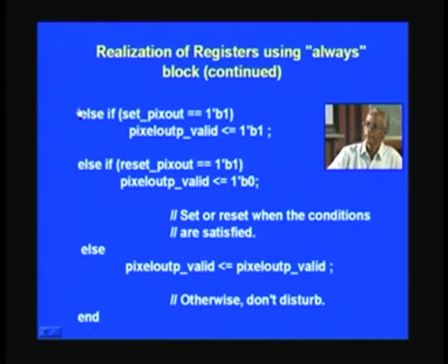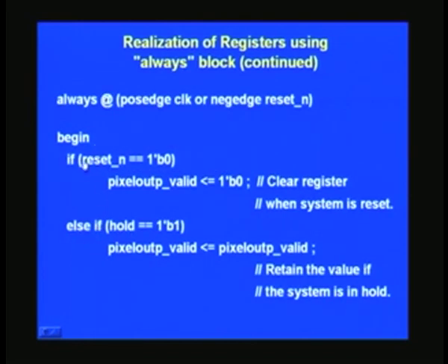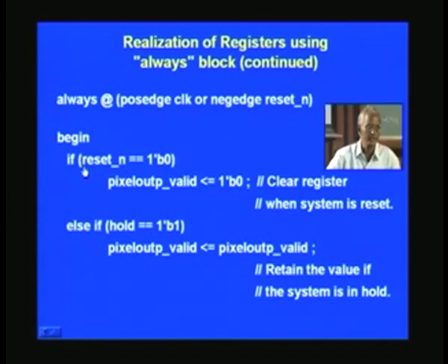And now you have seen the if, else if and finally else structure. If you just count 1, 2, 3 here and 4 and 5, from my experience if you exceed 5, your speed of operation will get hit. For example, if you are aiming at 100 megahertz operation on an FPGA, let us say field programmable gate arrays. You only get this by experience. So, do not try to add more than these statements. If you are still forced to add more statements, what you do is you combine this outside the always block and then restrict this once again to 4 or 5, right. The smaller the number, the better it is, the higher the speed of operation that you get.